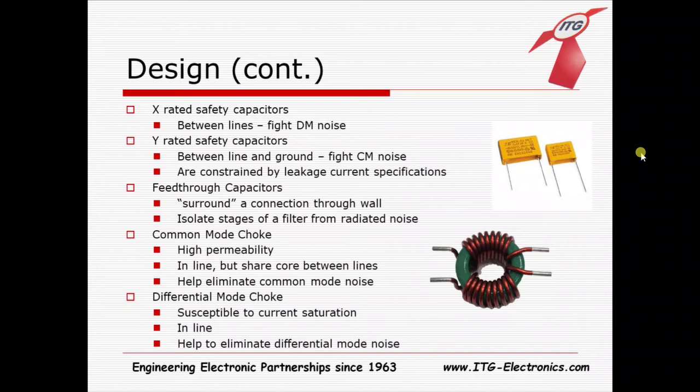And then the Y-rated capacitors are between any of the lines and ground. Those will help to fight common mode noise. One of the specific points on the Y capacitors is that they are constrained by the leakage current specification we mentioned in the design parameter slide.